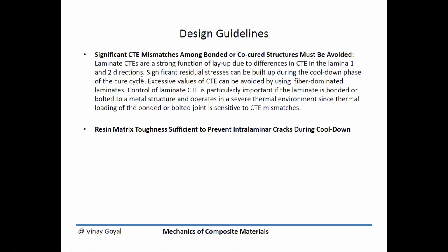As we said, laminate CTEs, coefficients of thermal expansion, are a strong function of the layup due to the differences in CTE in the fiber direction versus the transverse direction. Significant residual stresses can build up during the cool down phase from the cure temperature down to room temperature.